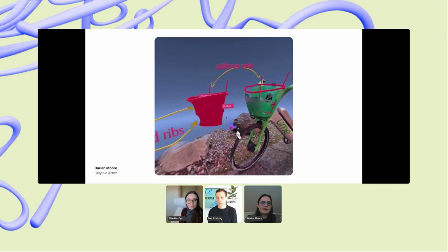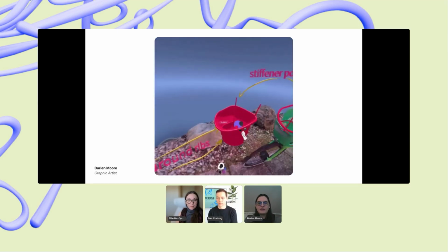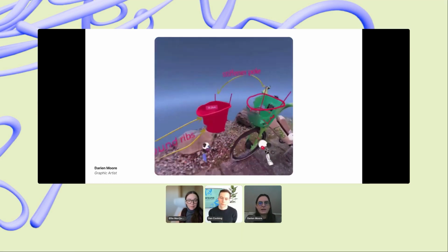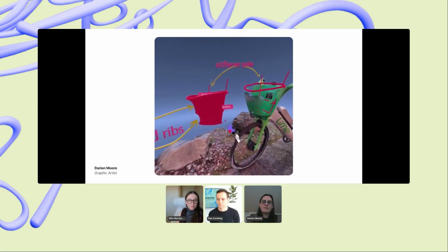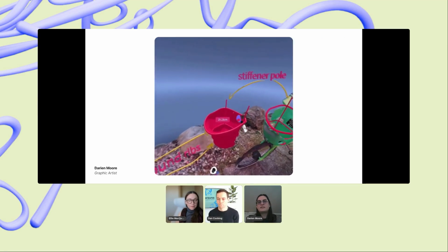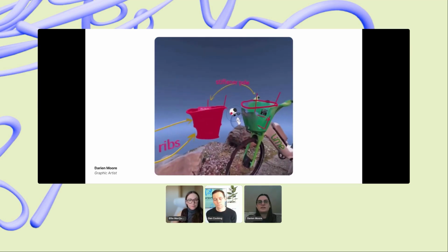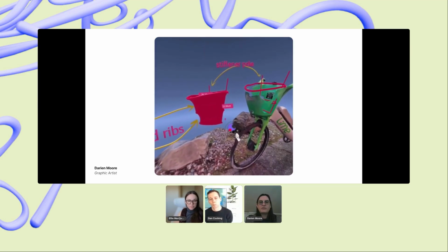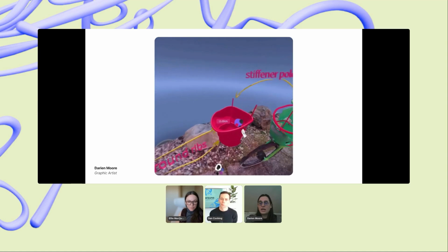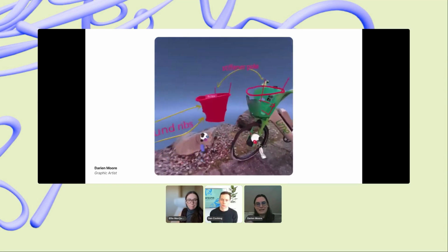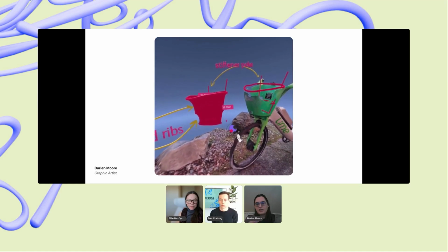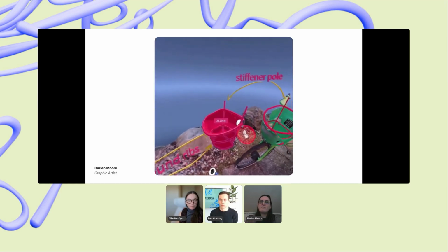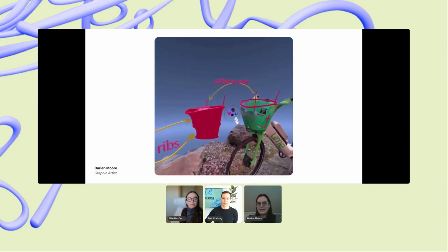Definitely. You can see in that slide there, the surrounding environment really helps with immersiveness. So trying to capture that, I know you can mask that off, but having that there was helpful for immersiveness and scale. But the two things I really picked up from this: one, locking the scan slide. So locking your vertical lock and the scan slide as its own layer really helps with not moving it by accident.